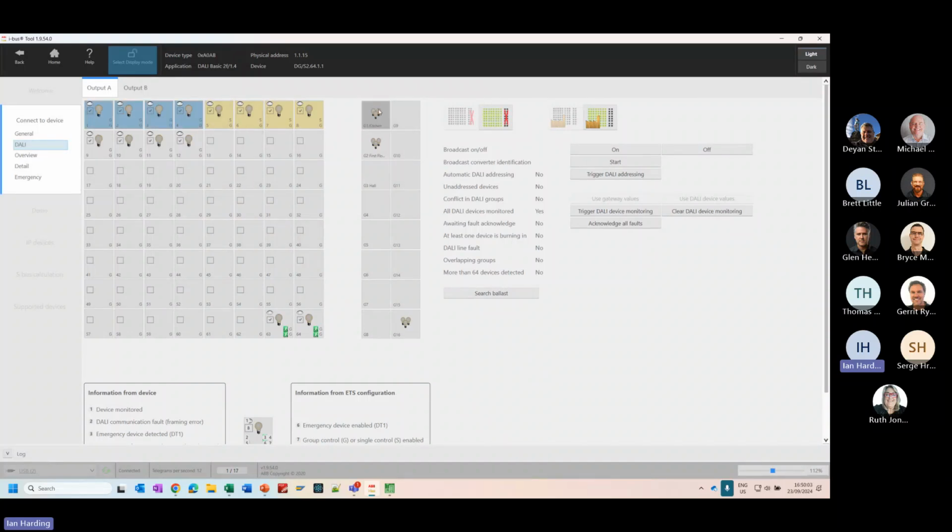I have, say, my kitchen group set to those 4. My first floor is set. I've nothing connected to my hall. And this is where my conflict is, because when I configure the device in ETS, I've told it that I'm setting all the DALI devices up my line in DALI groups, which is well and good, and it's happy days, everything, we can work DALI groups.